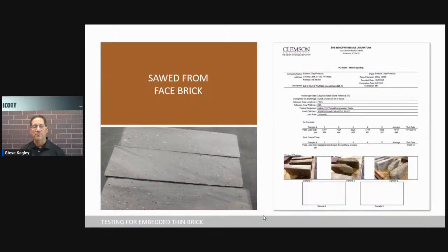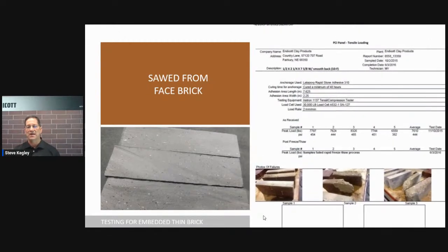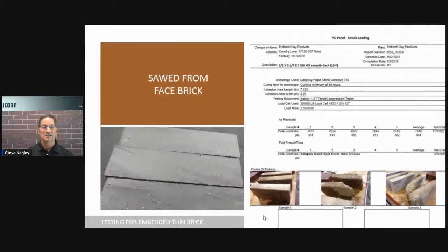Then we took some of our brick and we just saw cut the face off of them, the regular extruded face brick. And you can see what happened to the delamination in the pictures there. Two of the samples had nothing left to test after the 300 freeze-thaw cycles. And most of what you see, everything failed. So we know that the water absorption, from our own experience, is something to take into consideration when you're looking at thin brick material for embedding.